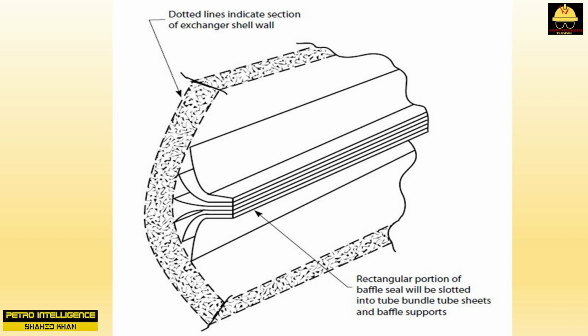Also, unless great care is taken by maintenance personnel when installing the new or replacement longitudinal baffle sealing strips, the heat transfer efficiency of the exchanger will be greatly reduced after it is returned to service. As a result of this deficiency, most operating companies severely restrict the use of two-pass shell-side heat exchangers.